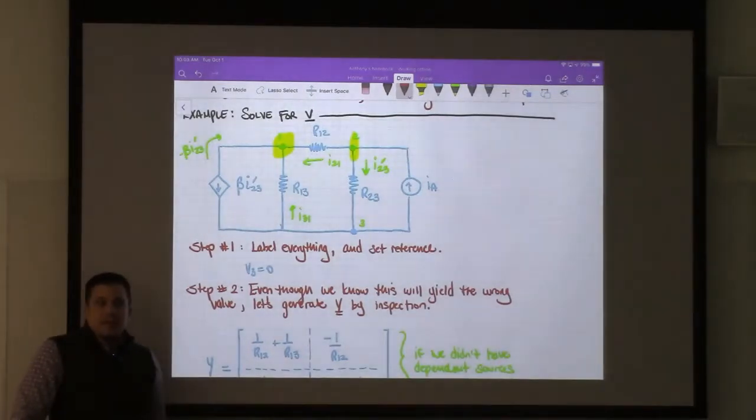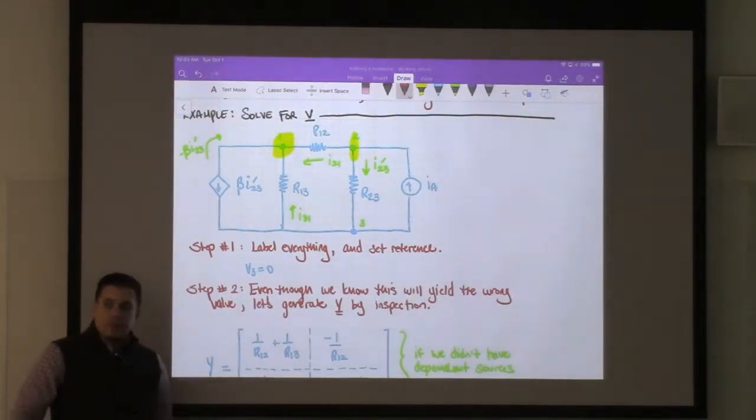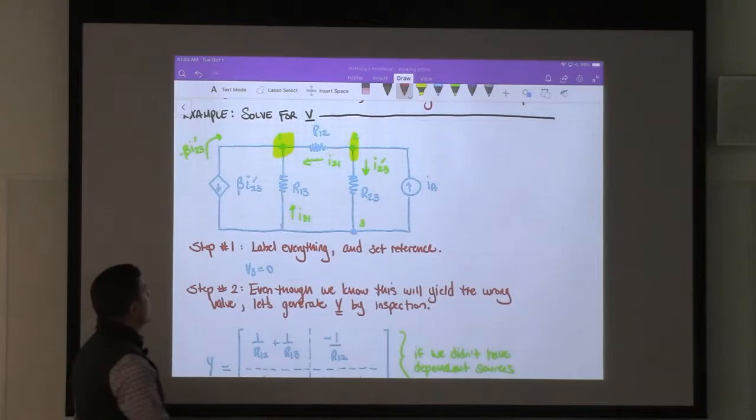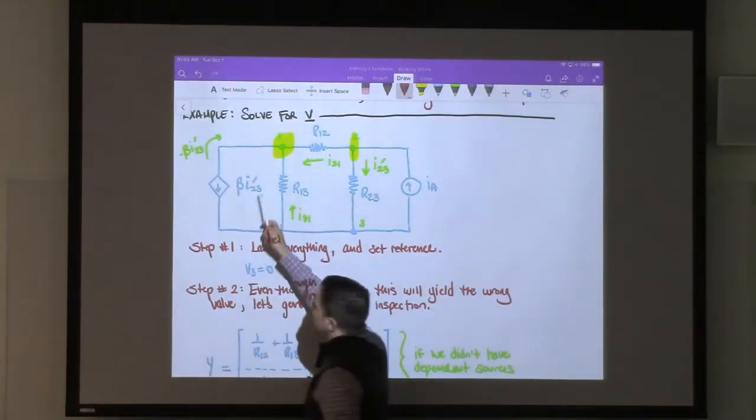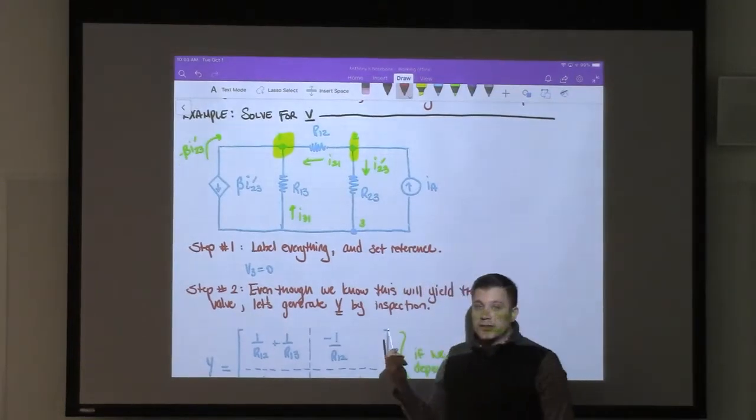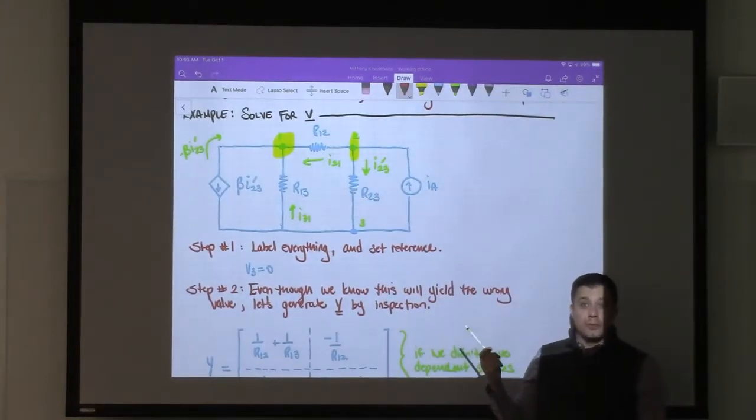So what is it that we're solving for? In nodal analysis, generally, we know... Bingo. If I were to replace this with an independent voltage source, I don't need to solve for V1 anymore. That's known already.